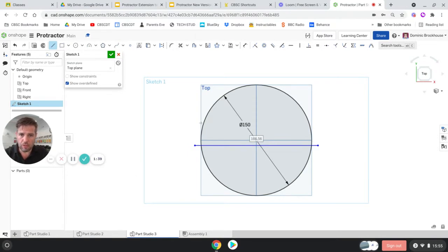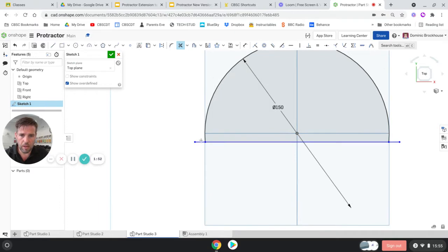So after drawing your line that cuts through, you are then going to use this trim tool, and snip off the bottom part of the circle so that we're left with the semicircle plus a little bit extra there. These bits, if like me, you've drawn them a little bit oversized, need trimming.